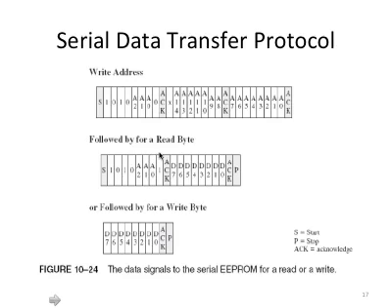This 1010 is the indication that this is an access to the EEPROM chip. Although in our circuit we only have the EEPROM chip, you may have cases where on that same bus, same data line, you connect other types of chips. It's very possible. So this 1010 is an indication that I'm going to access the EEPROM chip.